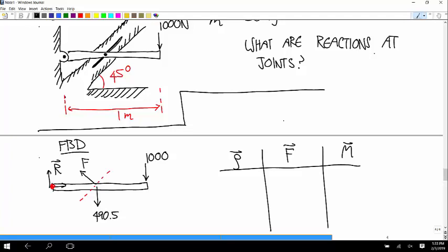Okay, so now we'll go through these loads one by one. First is the R force vector. What's the row vector for that? Yep. And the components, there's an X and a Y, but no Z, because we're in the plane. And the cross product is zeros.